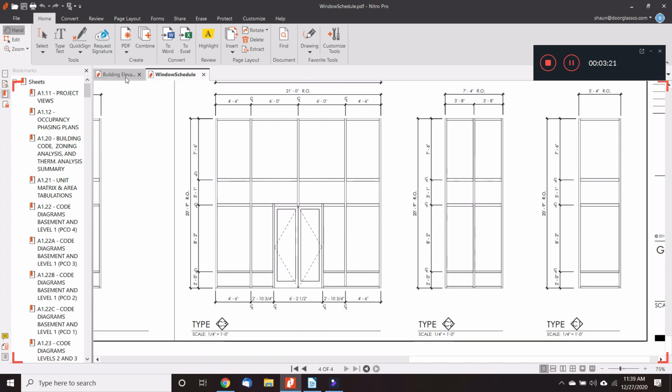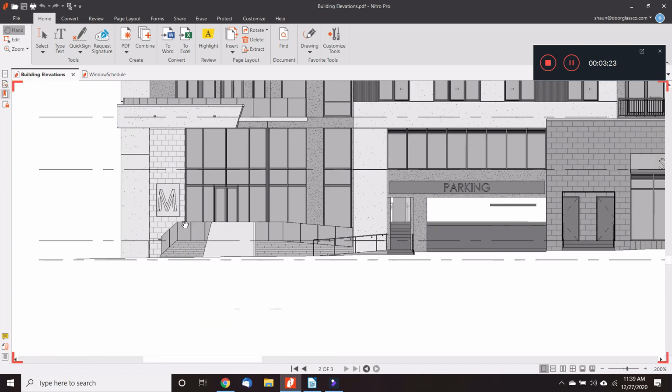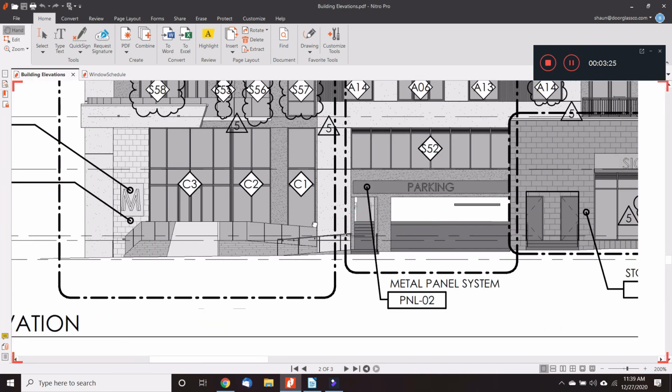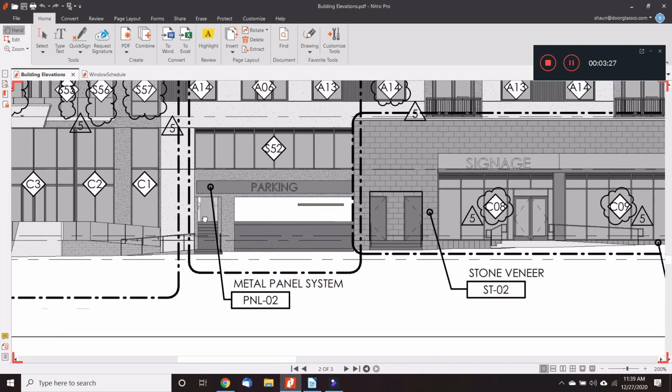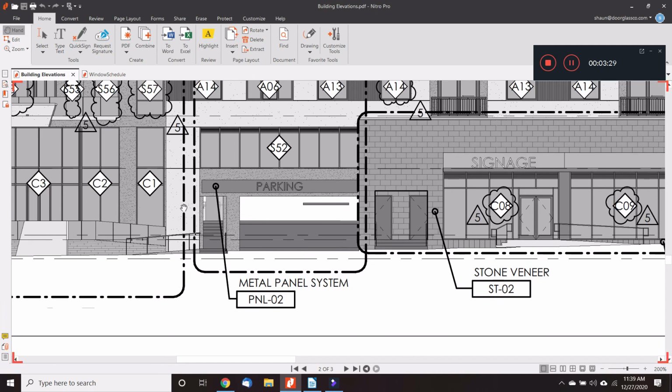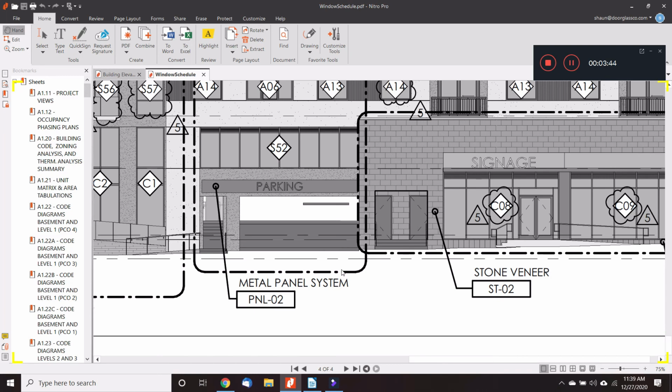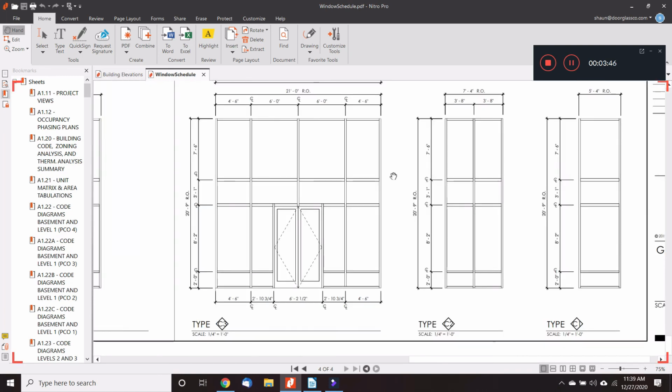It's important to keep in mind that we're building a building with other trades, and there could be a band of stucco that's supposed to line up with the horizontal. The contractor that installs that could potentially misalign it by half an inch or 1 inch, and then if we just fabricate a window to what's on the window schedule, these dimensions, when we put it in the opening, it's possible that it doesn't line up.